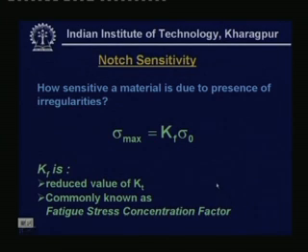Then comes another phenomenon which is noted as notch sensitivity. What is this notch sensitivity? You can see it is written, how sensitive a material is due to presence of irregularities in a machine member. Actually, the theoretical stress concentration factor for which we had a discussion right now is not totally applicable to all materials.